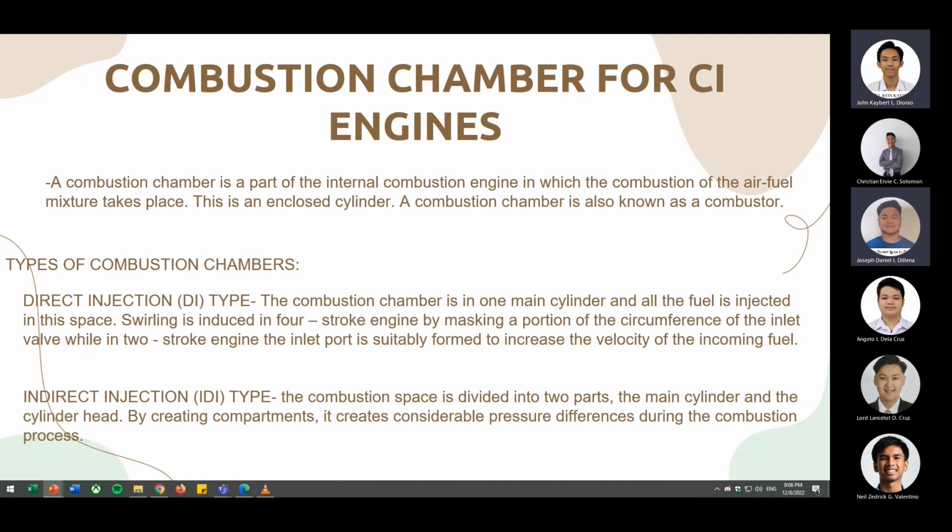The next one is the indirect injection, or IDI type. In this type of combustion chambers, the combustion space is divided into two parts, one in the cylinder head and the other in the main cylinder. Fuel is generally injected in the part which lies in the cylinder head.